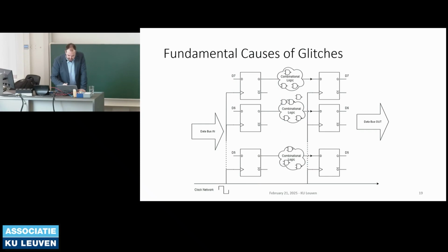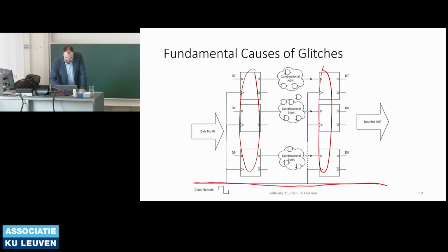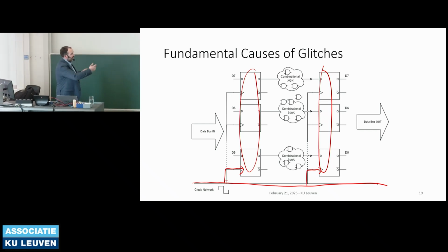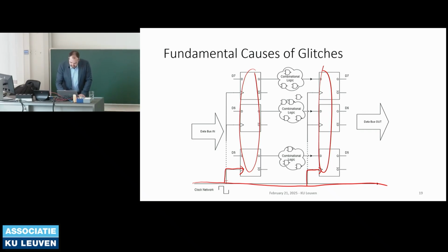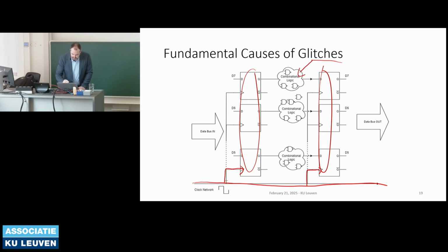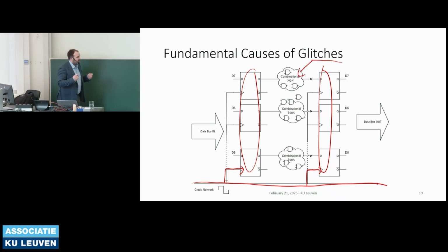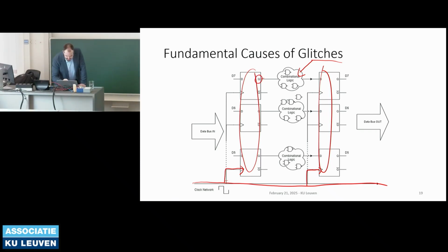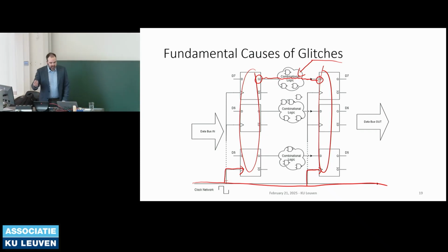Why we can glitch this so effectively is that we basically have this design where we have these flip-flops. The flip-flops get a clock, right? So a fundamental part of digital systems is we have this clock. Your desktop computer is running at gigahertz potentially. That's how fast this clock is running. That's how fast data is moving between registers. In between this clock network, this combinational logic is a little bit slower. So that's what sets our maximum speed, because between each clock, data needs to get from here through this combinational logic to here. If it doesn't make it in time, the wrong data gets loaded.